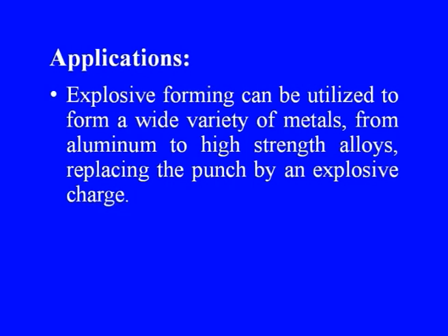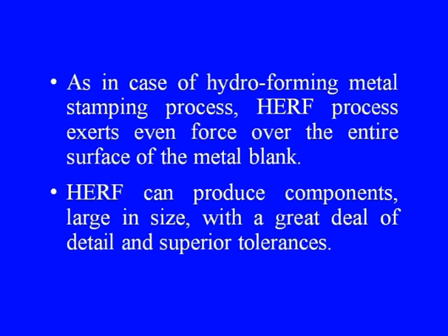Now, let us look at the applications of the process. Explosive forming processes can be utilized to form a wide variety of metals, from aluminum to high strength alloys, replacing the punch by an explosive charge. As in the case of hydroforming metal stamping processes, high energy rate forming processes exert even force over the entire surface of the metal blank.